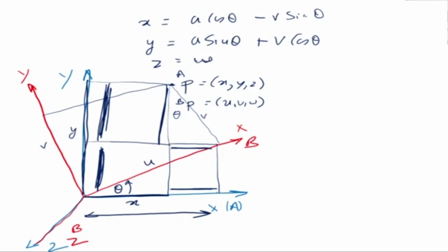So what we see is that it's very easy to obtain this relationship. There's nothing to learn by heart. Once you make this geometrical construction, you know what the matrix is. And the interesting part is that for x and y, only those cos and sine change positions. Okay, so what we have got is the rotation matrix. We write it as R_A_z by an angle theta.